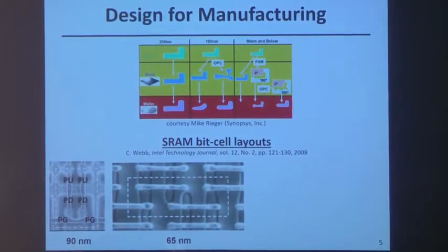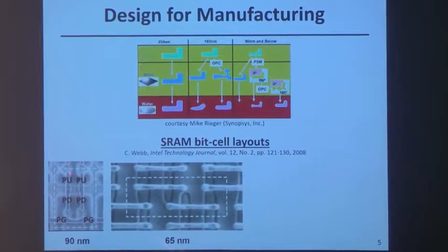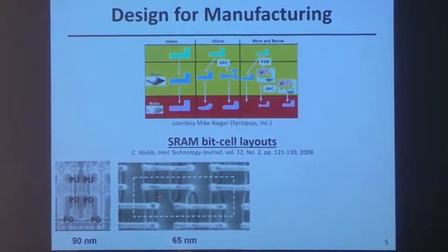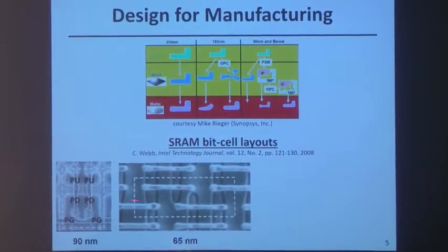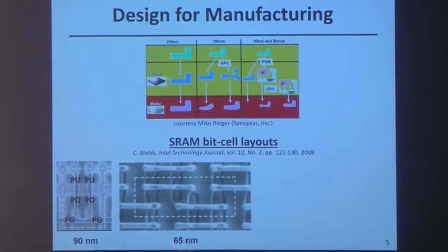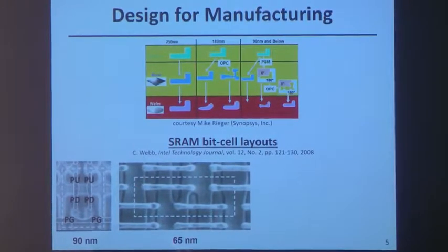So if you look at the size of this rectangle, which delineates the SRAM cell with 6 transistors, it is bigger than this rectangle because we're trying to show them proportionately. So the industry went to a larger layout in order to facilitate straighter features that were easier to print with good fidelity. If they could print these with better fidelity, then they can make them smaller. Even though this size is larger, like 150 F squared, where F is the minimum feature size, you can actually go down to smaller F.